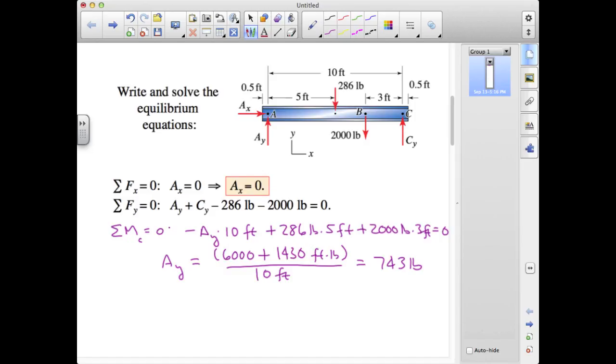Is there any other point where we might take moments? We can choose any point we like, but other than A or C, the moment equation will contain more unknowns and therefore make the solution more difficult. It will turn out, when we discuss rigid body dynamics, that it is often useful to take moments about the center of gravity, G. For completeness, let's do that here.